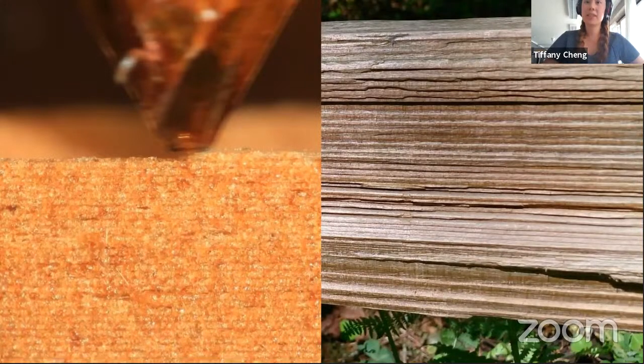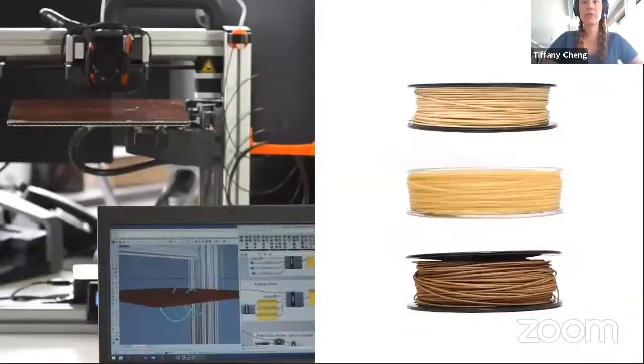So instead of sourcing natural pieces of wood, we can use 3D printing to structure the material and tailor its internal composition through the paths of material deposition. To 3D print, quote unquote, wood, we use the fused filament fabrication, otherwise known as FDM, fused deposition modeling 3D printing technique, to construct these bilayer units.